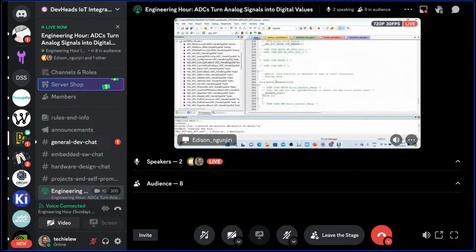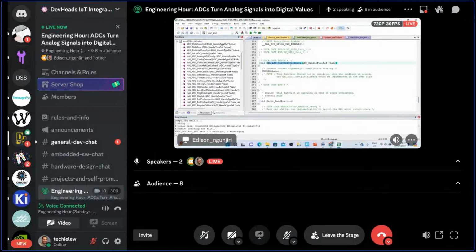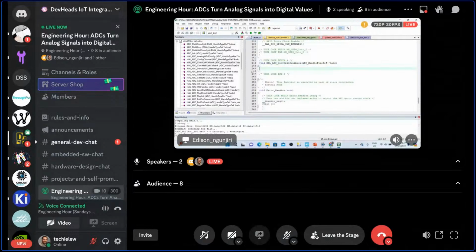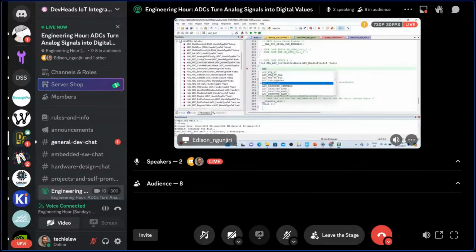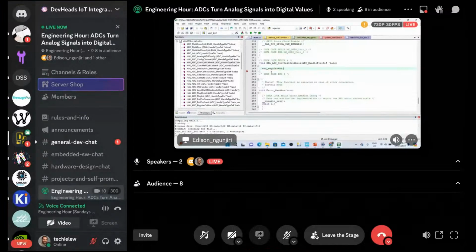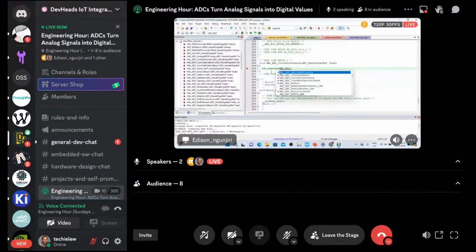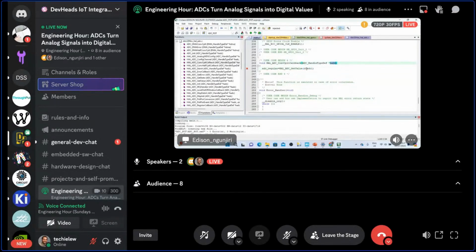And we shall copy this at user code begin 4. So this is HAL_ADC_ConvCpltCallback. Okay, so we can get our reading from this point. And I can say ADC regular is equal to HAL_ADC_GetValue, and I'm getting this value from hadc1, or simply I can just pick this.